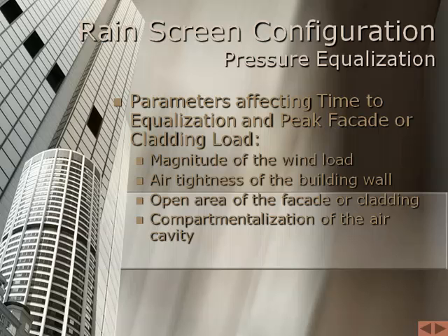In larger buildings, additional compartmentalization within a facade can address differences in pressure across the building face. The size of the compartments should be based on the extent of pressure variation across a given area. Therefore, smaller compartments are required at the edges of walls, while toward the center of a building face, where pressure is more uniform, the compartments should be larger. Determining compartment size requires a judgment by the designer as to acceptable pressure variations over a compartment.